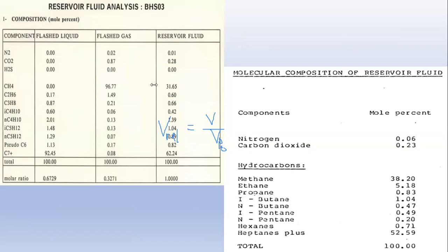Because it's collected at the surface, the gas has already liberated out of the oil column. So definitely there might be some errors. So you have to confirm that yes, the compositions are completely intact. I believe in the next session, before we jump into the PVT modeling, we'll do data QC. But what you really need is the reservoir fluid mole percentage to run the analysis. But you can actually use this to QC.